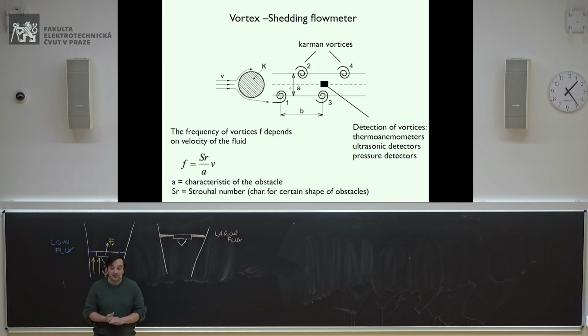A very interesting phenomenon is the one used by a flow meter based on vortex. Basically, it's based on an object which you put inside the place where the flow is, not necessarily a liquid, any type of fluid, also gas. You want to measure the stream, and when you have this bluff body here inside, it will create some vortex. So if you have here a velocity of fluid from the left-hand side going in this direction, the fluid will have to go around this object, which obstructs the flow that you want to measure, and it will create some vortex.